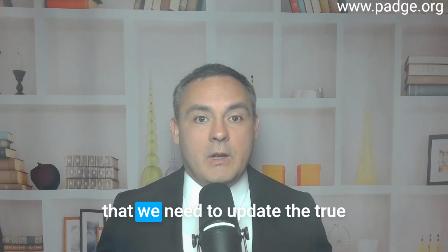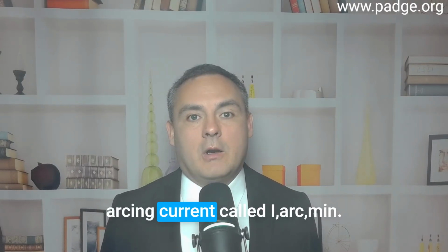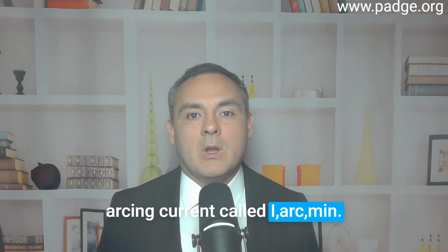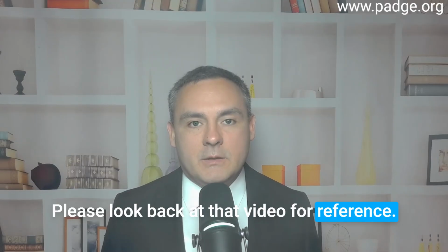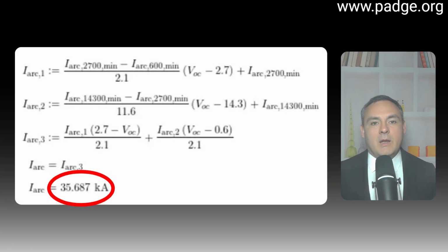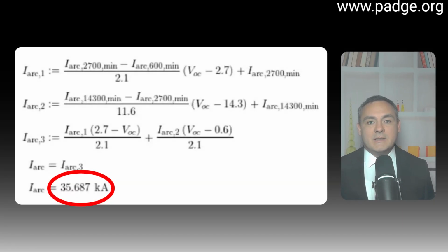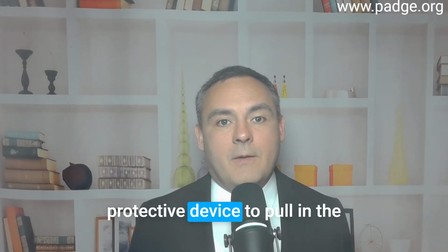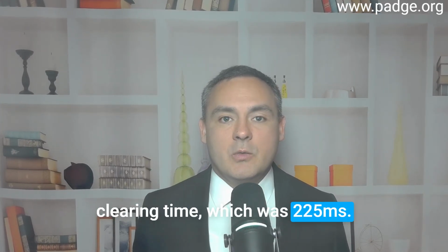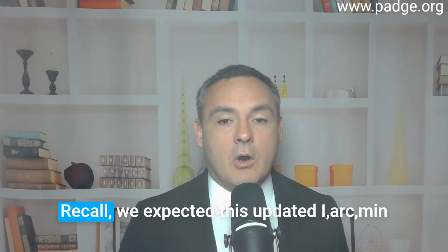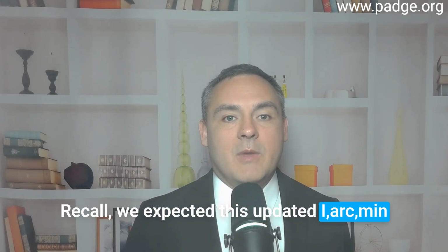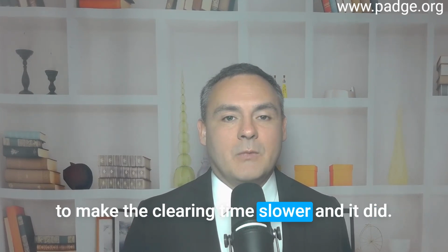Recall that we need to update the true arcing current called IArcmin. Please look back at that video for reference. We calculated the IArcmin to be 35.687 kA in the previous video, and then looked at the overcurrent protective device and pulled in the clearing time, which was 225 milliseconds. Recall, we expected this updated IArcmin to make the clearing time slower, and it did.